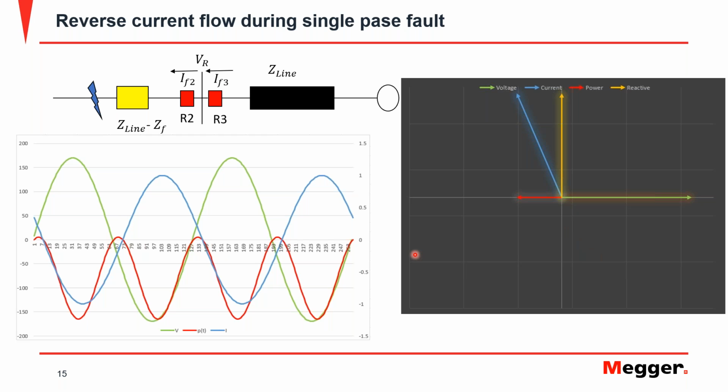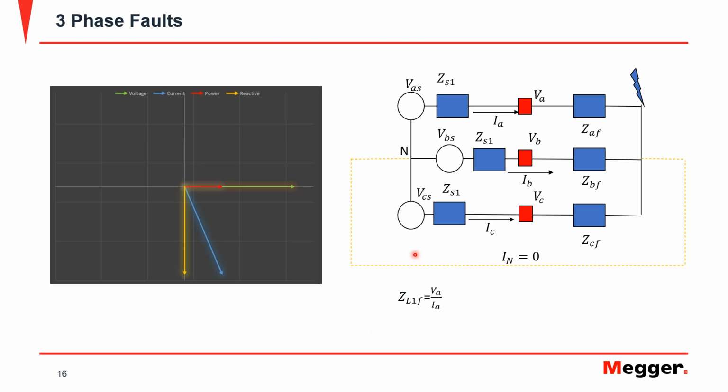Now, this tells us that we can use the phase relationships between voltages and currents to determine directionality in the system. Now, that is never as simple. This just tells me the parameters that I can use, but the implementations of such directionality determinations or directional functions depend, of course, on the types of faults that I have in the system.